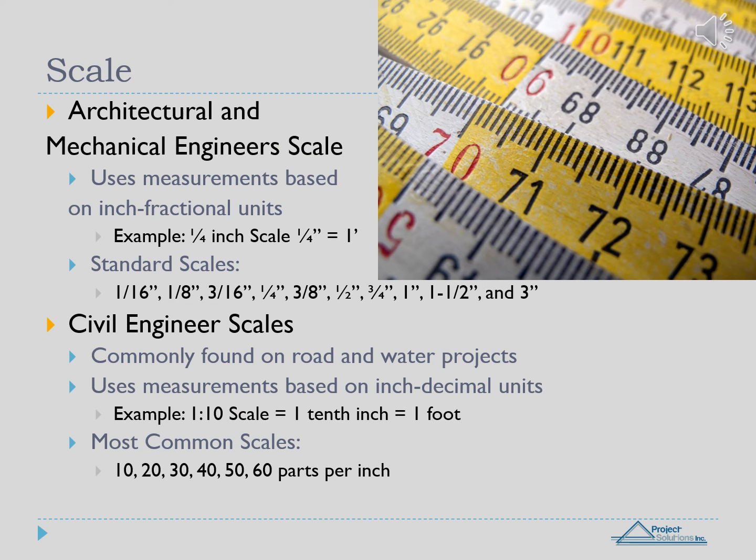Understand scales and how they are being used. There are two different types of scale to be aware of: architectural and engineer scales. Construction drawings will indicate the scale on the same sheet as the drawing you are looking at. Architectural scales are normally based on fractions of an inch, so 1/16 inch, 1/8 inch, 3/16 inch, quarter inch, etc.